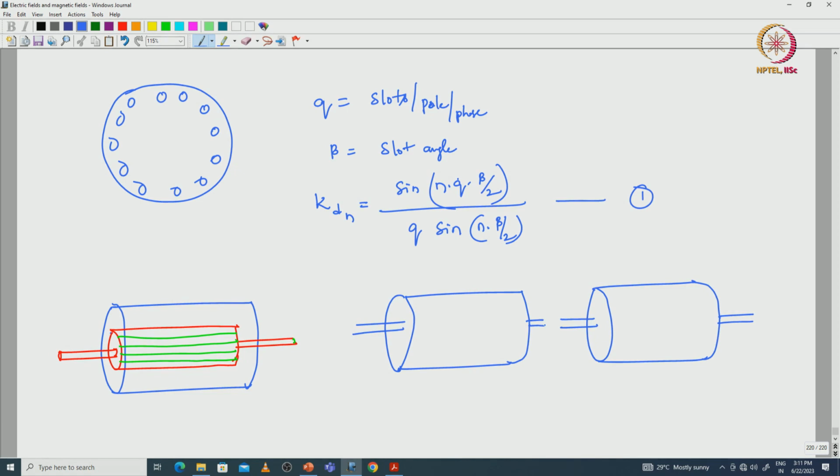Rotor structure only I am considering. The rotor whose bars do not have any skewing, we can see the straight bars, and with skewing we can see the bars will be in this manner. This is the skewed rotor bar, where all the bars are placed in this manner.